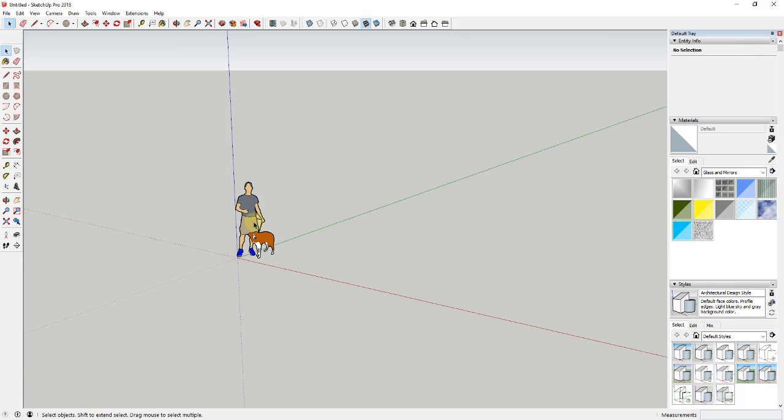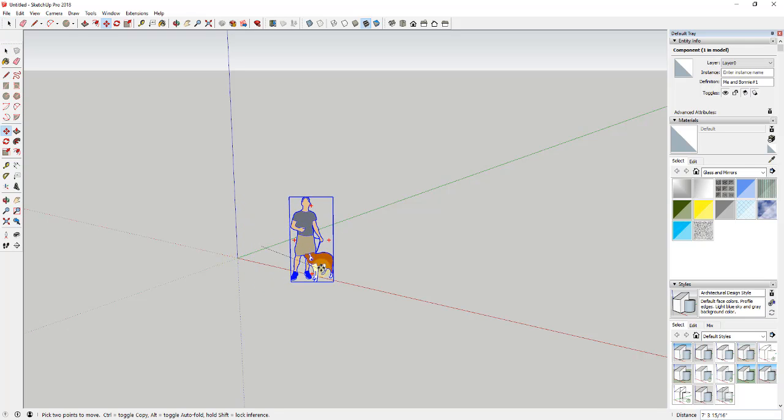All right, so as always, what we're going to do is we're going to rough out our floor footprint. So in this case, this is going to be kind of a larger area. I'm going to move my default model out of the way because I like to start by centering everything on the origin. It just gives me a good place to start. But I'm going to start off and just draw probably a 50 to 60 foot long line. We're going to say 50 feet long.